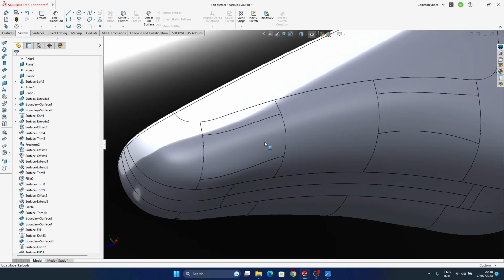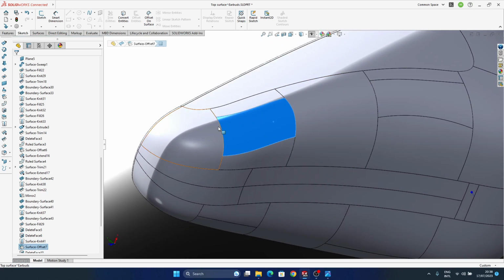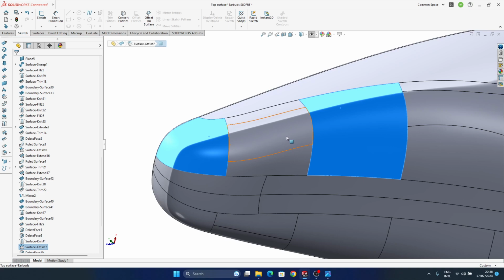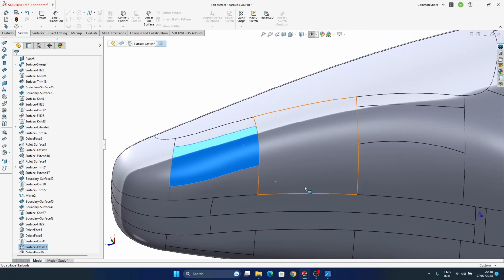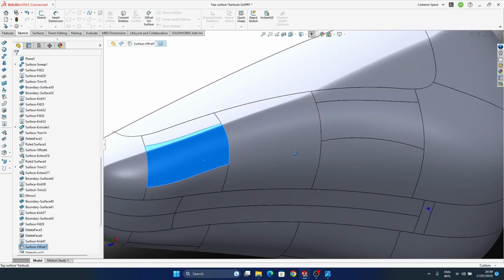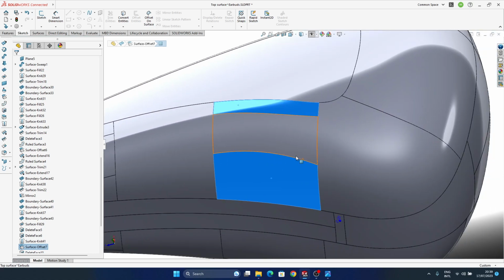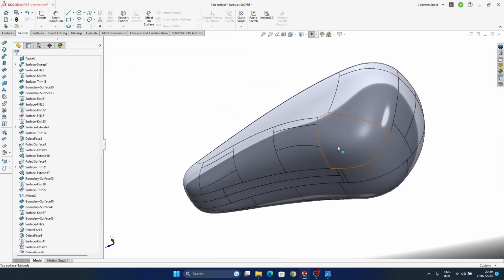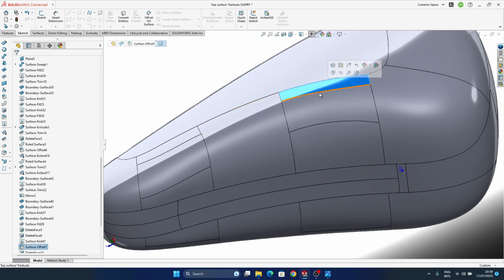The second thing that I did, because the whole geometry is quite organic, in these areas I made the blend between the two, this fillet and this fillet. Let's call them fillets. They are just joint surfaces, so that I can guide the software on how to make the continuity and resolve the surfaces. This one worked directly as it was, but this one I had to make the surface and then cut it using splice and only then create these two filled surfaces. It's not very pretty, but again, all this is more for learning. It's not necessarily super accurate, and if you watch all my videos, by now you should have all the knowledge to actually build these kinds of transitions.